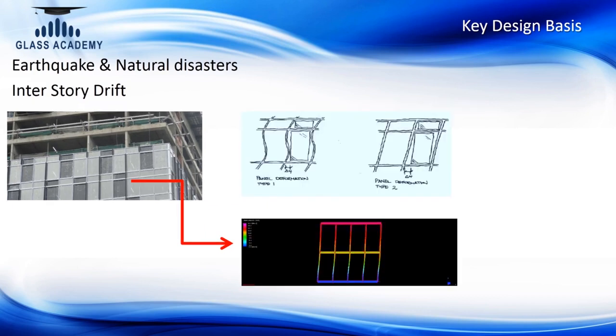Here we could go into a little more detail with a video showing how this building sway will impact the framing elements in particular. As you can see the building swaying, when the framing changes to red, it is highly stressed. As you can see, this frame is imposing a lot of loads onto these members when it is swaying. This video is showing primarily this linear sway condition. In this condition, the frame will have more impact relying on the weaker axis bending.